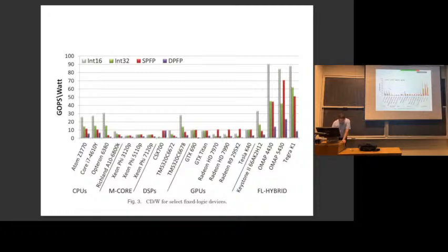These are the processors, okay? They prefer int16. They're more power efficient. That kind of makes sense. They get more SIMD like we talked about. Xeon Phi is really targeted at getting high throughput. Clearly has a fairly big power usage, so it's actually not as good for power efficiency. The DSPs were pretty bad for raw throughput, but are actually pretty good for power efficiency, so throughput per watt. And the GPUs are kind of in the middle.